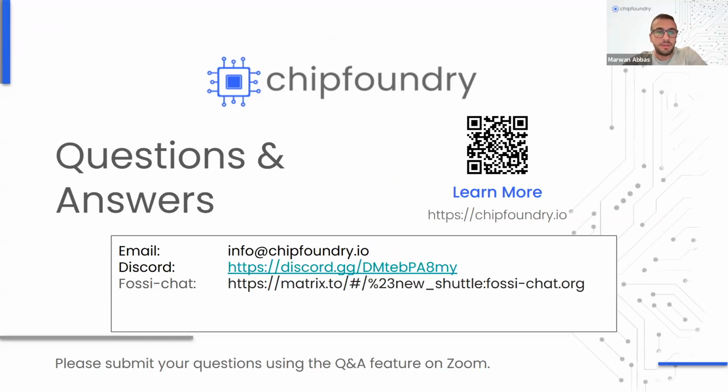So we have a question: to make sure that the documentation states it's 1 KB, is it in bytes or bits? So the 1 KB, is it bits or bytes? Yeah, so it's a 32x32 cell, and currently each cell can only be a binary, so it's 1 Kb small b. So 1024 cells with only 1 bit of switching in the X1 IP.